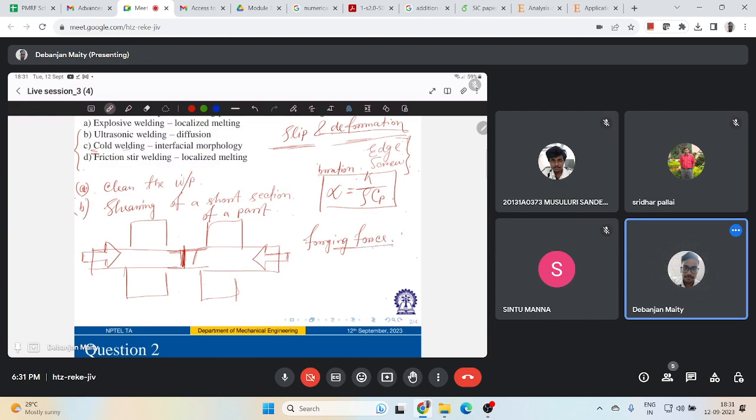Now, in terms of characteristics of cold welding, the metals must be ductile without excessive work hardening. Otherwise, at room temperature, you cannot do joining. If you are joining some hard metal at room temperature, you cannot deform it only by pressure. Like in friction stir welding, you basically rub the workpiece against the tool, and you have to raise the temperature of the material.